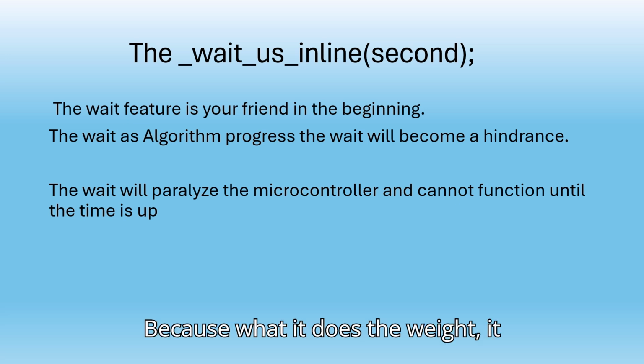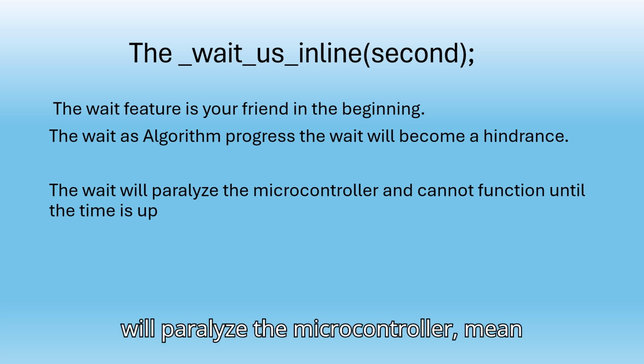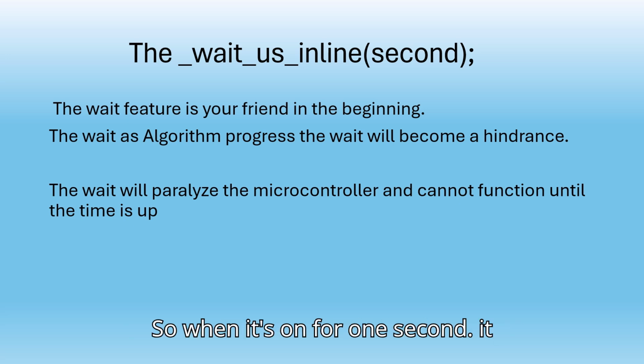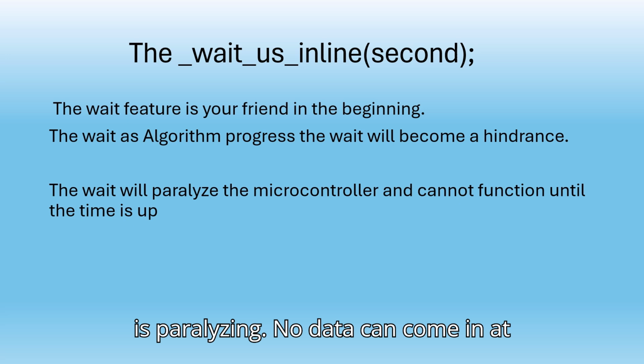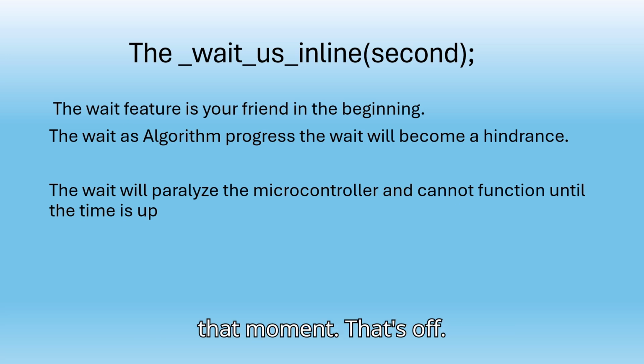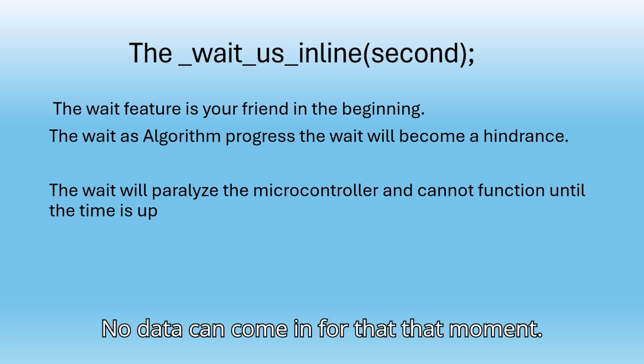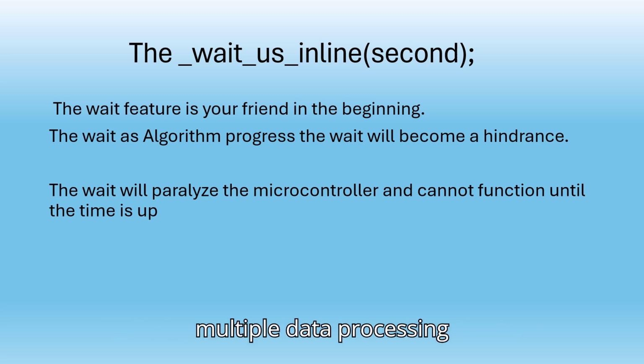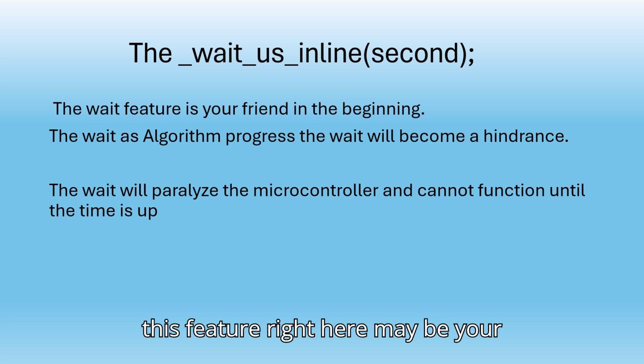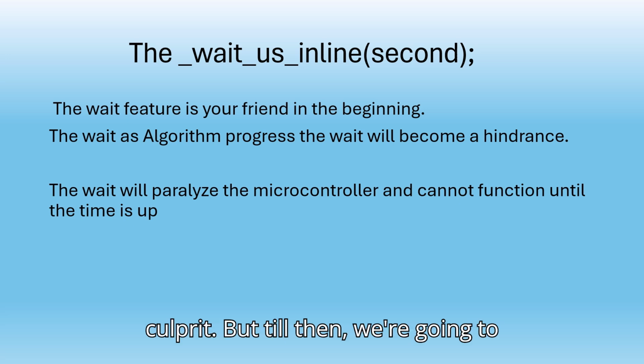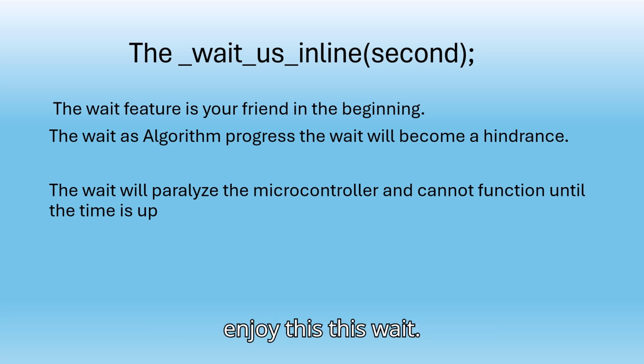Because the wait will paralyze the microcontroller, meaning it doesn't function until the time's up. When it's on for 1 second, it is paralyzed. No data can come in at that moment. When it's off, no data can come in for that moment. So if you're using a device for multiple data processing, this feature right here may be your culprit. But till then, we're going to enjoy this wait.